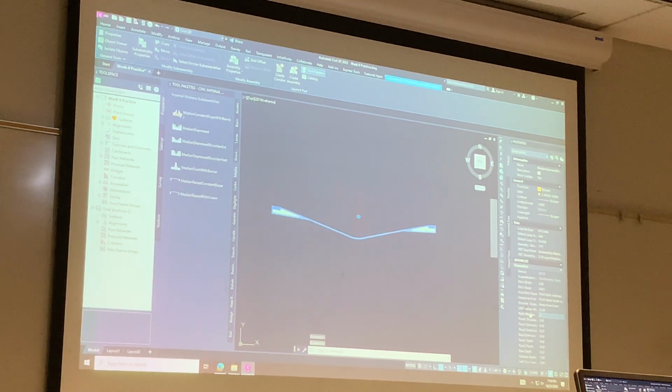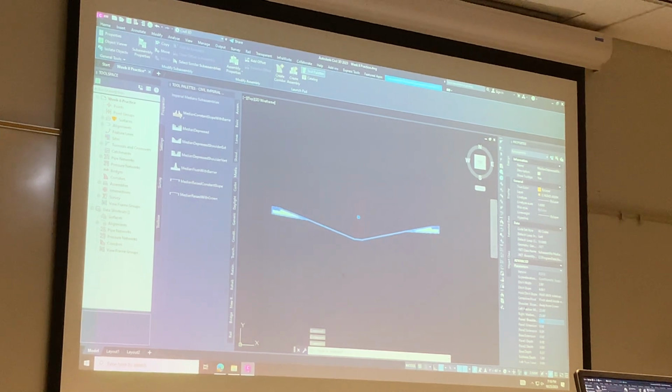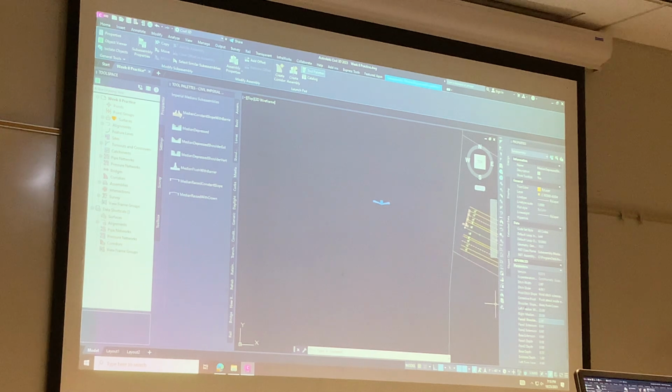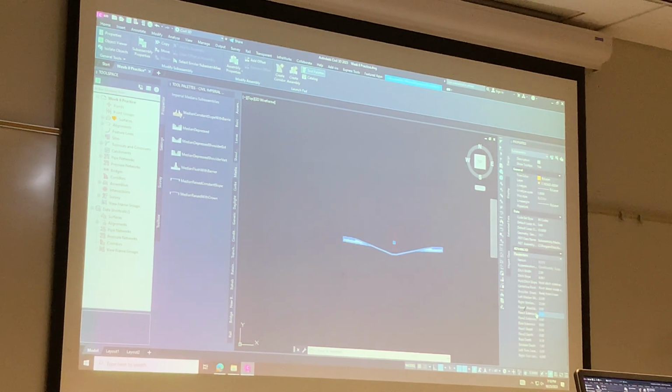Blue median, red median width. Paved shoulder was what? Was 5. 22. Or just the half. Okay, the rest of these properties look okay enough. If we had a different ditch slope, we might change it to a different slope. The Florida one's okay. I'm not going to lie, I found the properties.